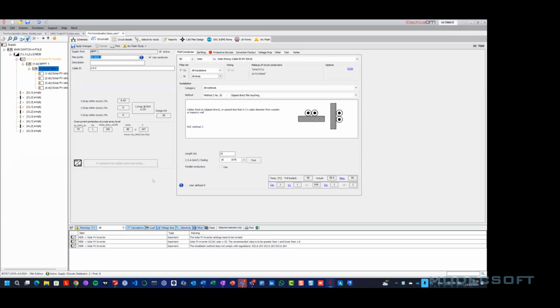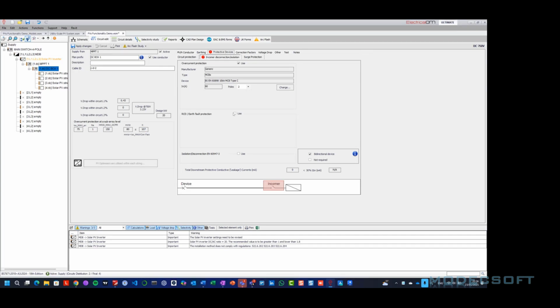The reason for that is, as we mentioned earlier on, when we are using power optimizers, we are not allowing any reverse currents in our strings. However, we have to properly size our PV string cables to satisfy the requirements of the minimum Iz here. The minimum Iz is based on our protective device here.